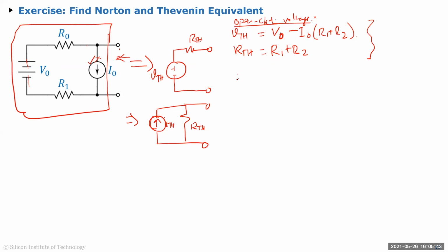So now let's find out the Norton equivalent. Let's say you didn't know the Thevenins. You find out the Norton equivalent. So Norton equivalent, say ITH, right? So ITH is you short circuit this, and you find out what this current is flowing in this direction or the opposite direction, whatever convention you choose. So here I've shown it in this direction. So let's keep it current in this direction. So ITH is now same thing.